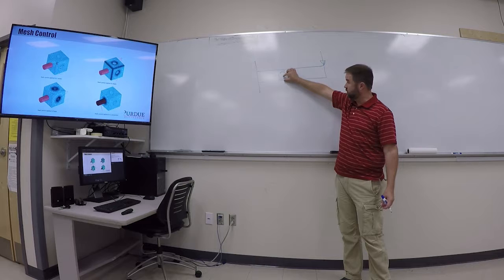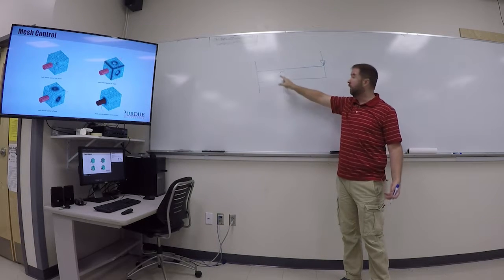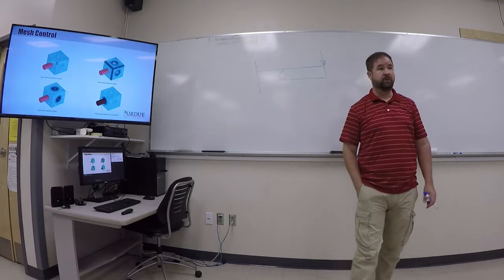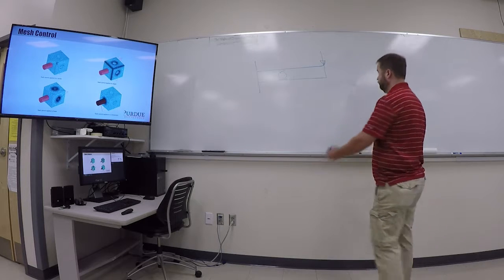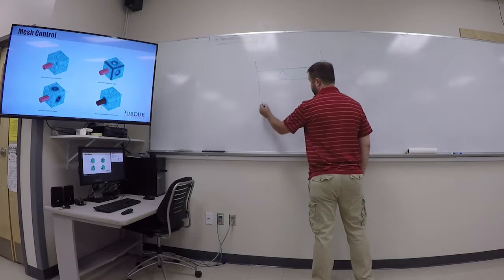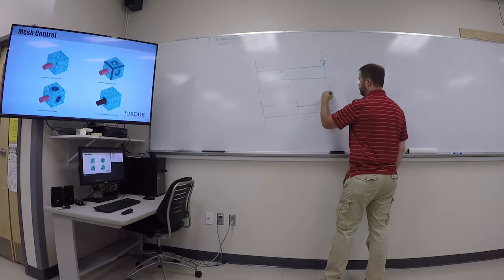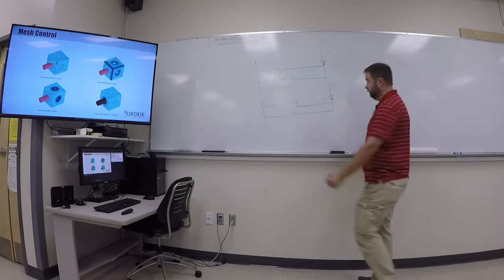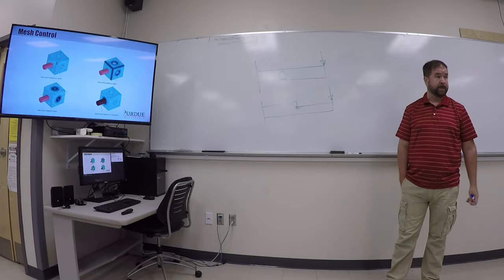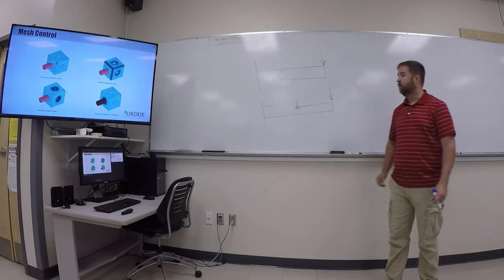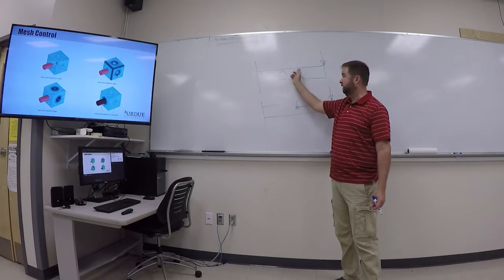Combination of, we've got a reduction in the cross-sectional material. There's less material there. And then we also have the effect that you guys learned in 211 of stress concentration factors, right? Or we could do the same thing, a beam that has a notch in it. We're going to get some really high stresses around the corner of that notch because of that notch being there.